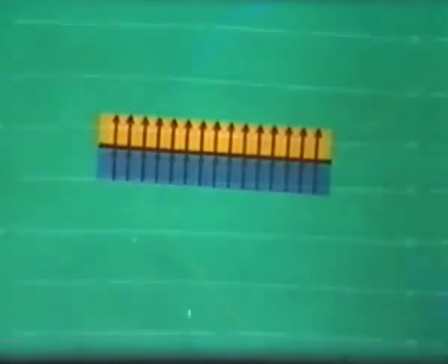Here is the flow pattern. On the upper surface, the pressure is less than atmospheric, as there's an expansion at the leading edge and a shock wave at the trailing edge. On the lower surface, the opposite happens, and the pressure is greater than atmospheric. Here is the pressure distribution. This area is a measure of the lift. The center of lift is at the midpoint of the wing. Unfortunately, a wing like this is not practical structurally.